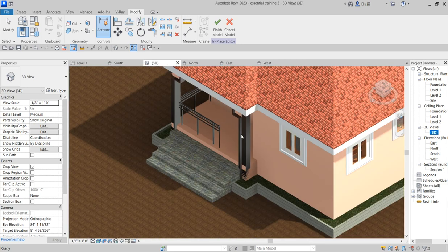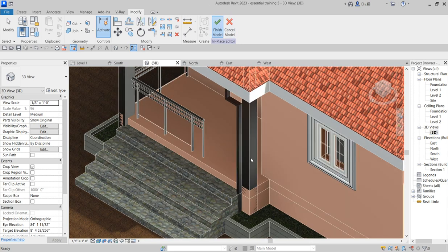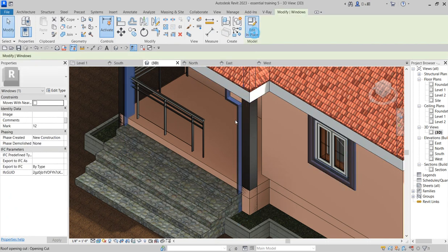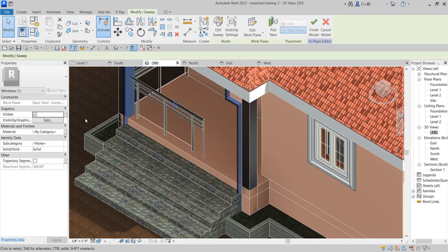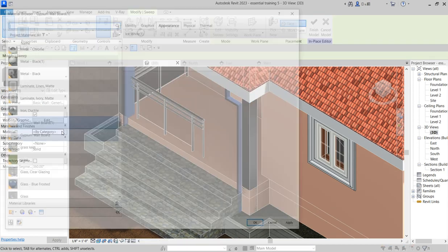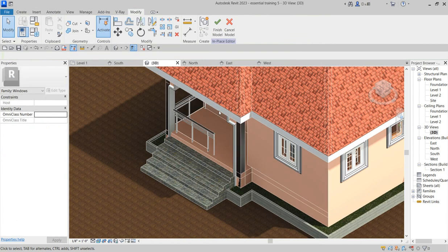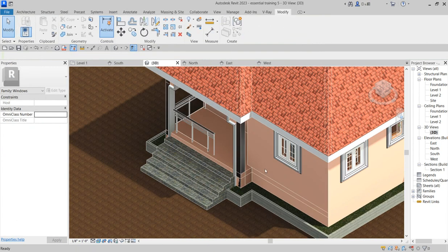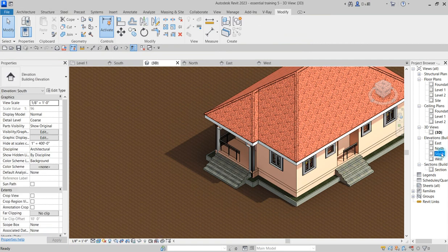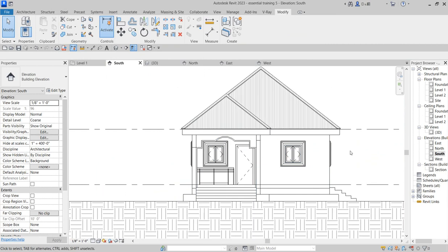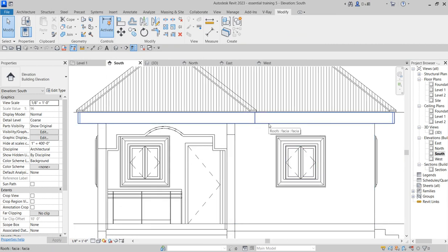and you see this is the flow of what you have created. So select that, say click finish, edit in place and change the material for yourself. Category, on top of material, let me use that particular white. Good. So do that and say okay. Go to elevations and see what you have done, whether it's right or not. So that is one part for that level.